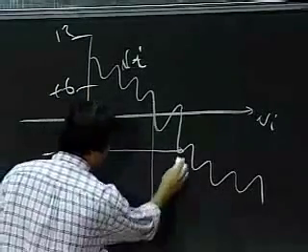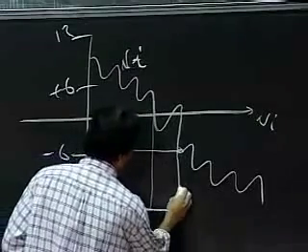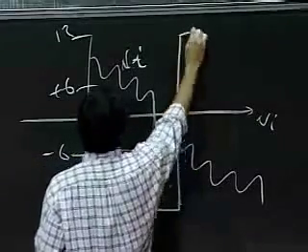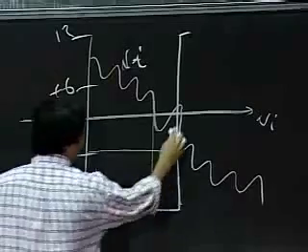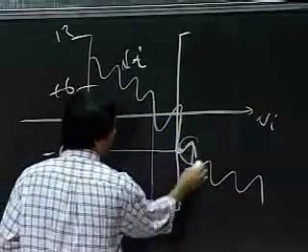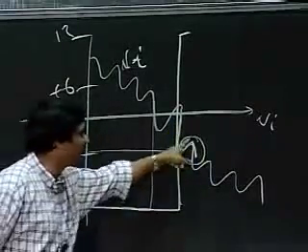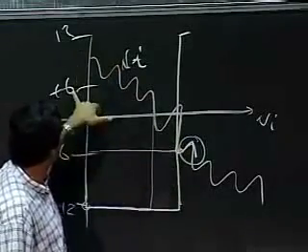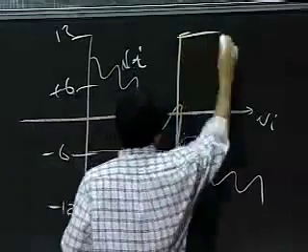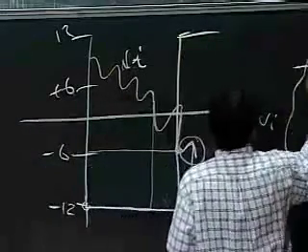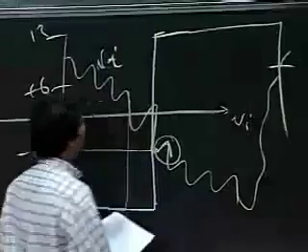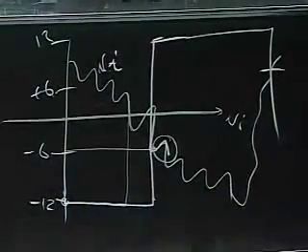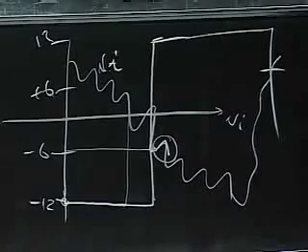So out here, I get to minus 6, and I switch state, and I go up to plus 12. And then this one comes up above minus 6 very slightly out there. Nothing happens because the next change will happen only when the input goes to plus 6. So eventually the input gets to plus 6, then I'm going to change state again. This is actually a really cool property and something that is completely non-obvious.